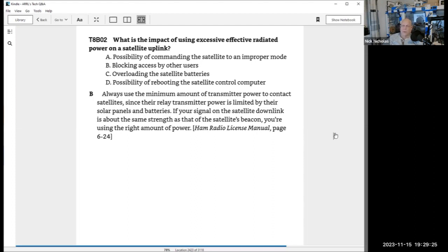Look at it this way: if the satellite is getting a 1,000-watt station coming into it, and it's getting a 5-watt station, it's going to send back proportionate to the 1,000-watt station. Let's look at it with numbers. Let's say the transmitter on the transponder of the satellite might only have 5 or 10 watts.